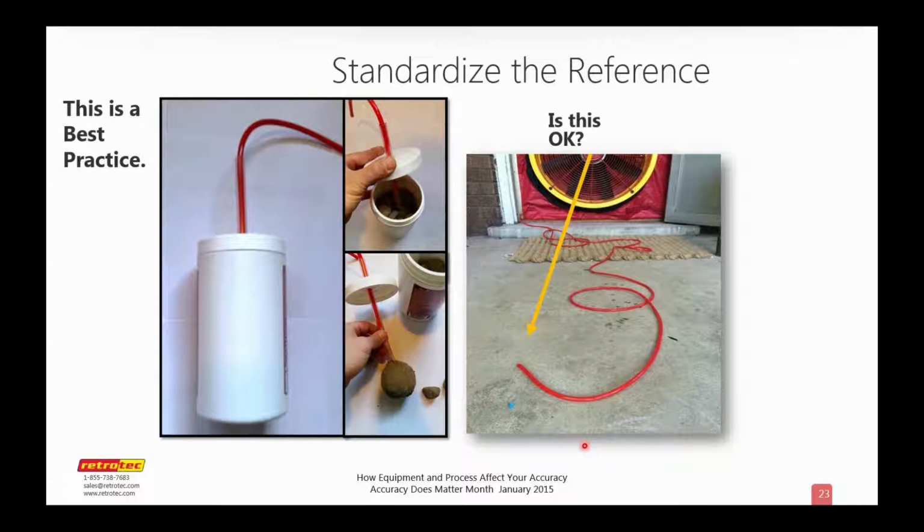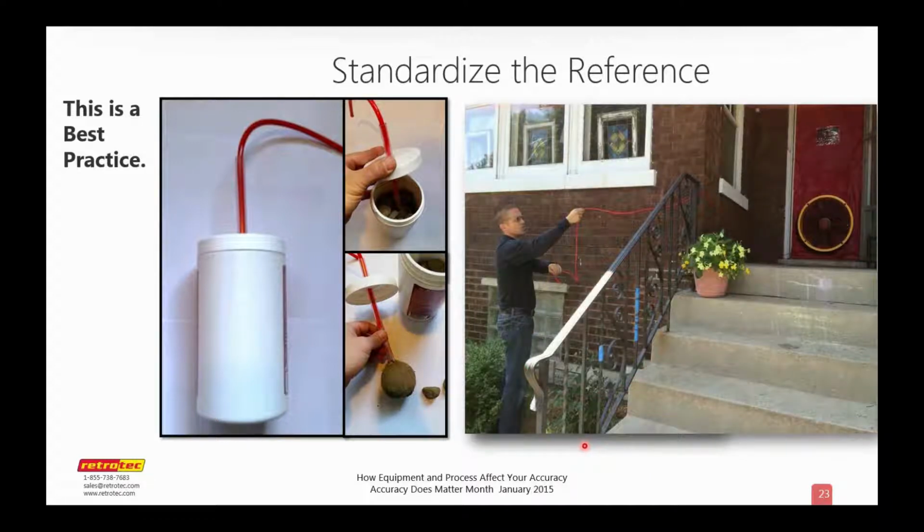Now, if you're doing retrofit, you have to make sure that everybody testing the house understands where the thermal boundary is. One shut door can actually make a completely different test, pre-post test, or give you an inaccurate result. So here's the idea. This guy is taking that reference hose out from in front of the fan, moving it over here. He's going to stick it into this little container, and then put it over here where it's hidden, away from that corner of the building where turbulence and wind can move around.